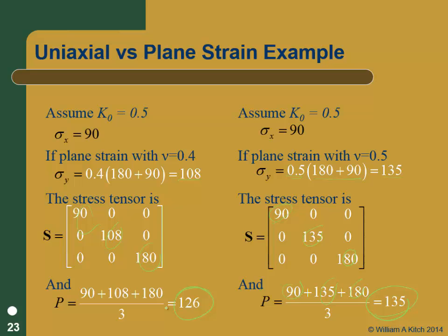What we're then saying is that plane strain conditions apply, and that we've got to know something about Poisson's ratio to understand what the stresses are in the horizontal direction. But it's not like there's no stress there. That wouldn't be plane strain conditions. That would be plane stress conditions. And so we've got to understand what it means when we make these assumptions.